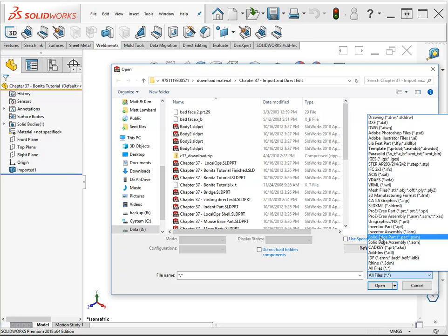Unigraphics and Solid Edge should be able to give you Parasolid data, which will be very reliable. The mesh data is currently mostly usable as graphics, but SolidWorks also has an add-on package that allows you to use mesh data to create NURBS surfaces. It's not automatic, it's not necessarily pretty or easy, but that's a tool that you might want to use.